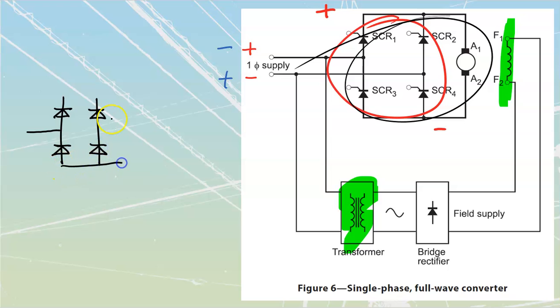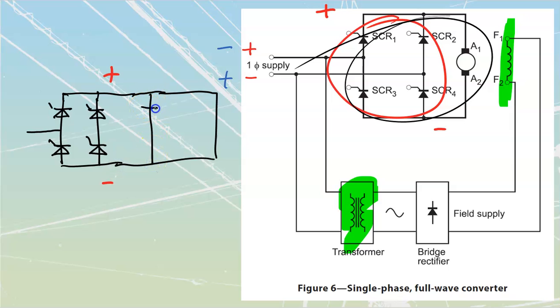Okay, so these ones here are going to go and convert my power into my DC. We'll stick a positive rail up top here, and a negative rail down below here. What that allows me to then do is run that through another set of SCRs over here. These SCRs are going to be biased in the opposite direction. Just draw all the way out to here and to here, where I'm now going to be using these for load control.